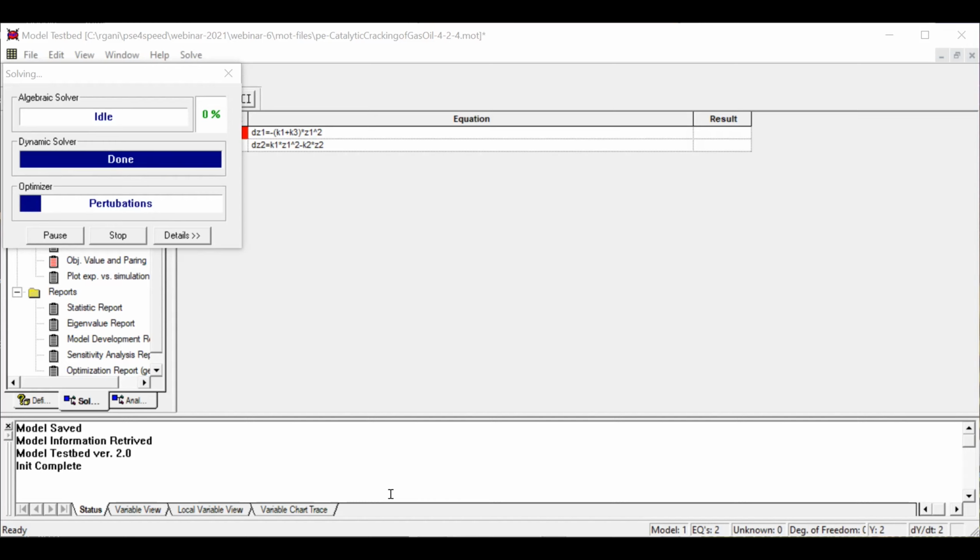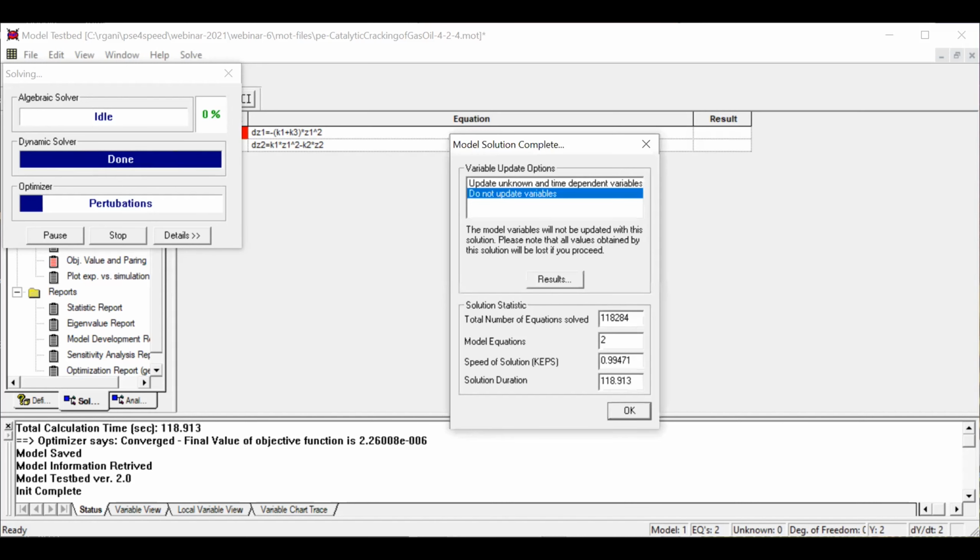And you will see that Biegler has a GAMS example on that. So that also we can do. We can convert the differential equations into algebraic equations through collocation, and then set up an algebraic equation based optimization. But since this is very fast, we can do all these together.